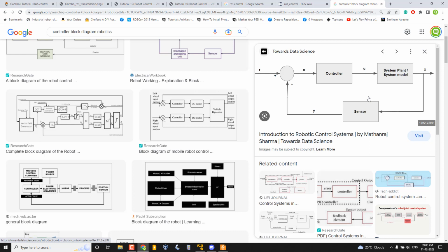It can be software or hardware. So the controller will be controlling the output. Like if you are giving 90 degree to the motor, imagine the motor is in 0th position, and if you directly give 90 degree, it will quickly move to the 90 degree, right? So that is not a smooth motion.